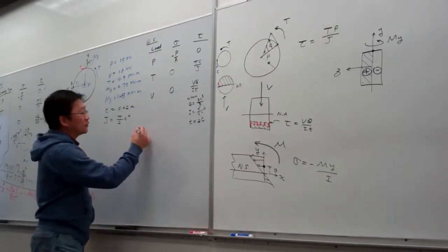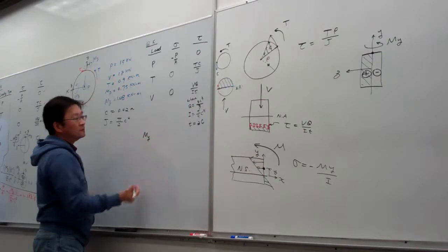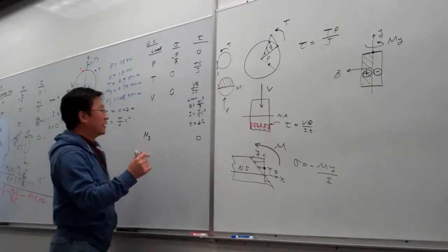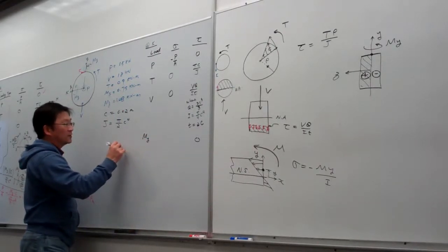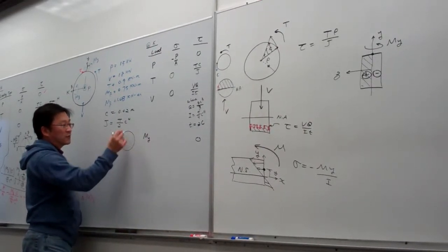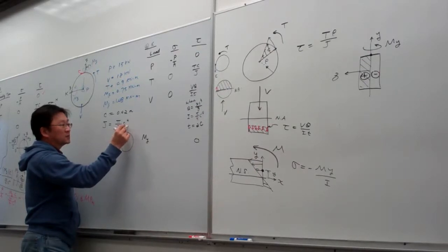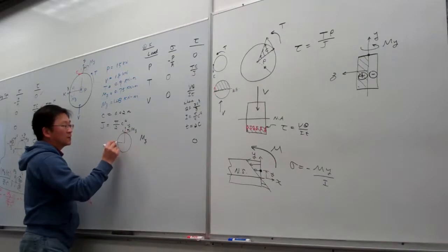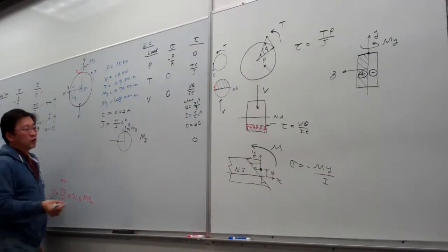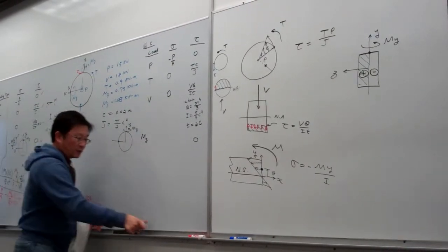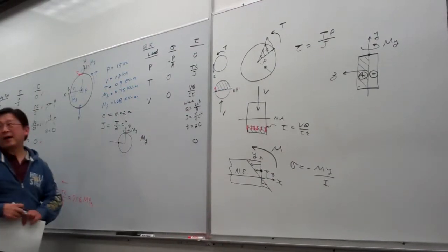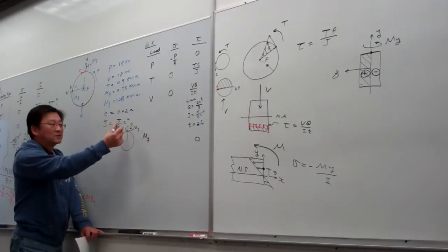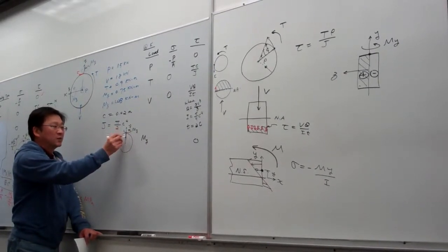And now we go to the MY. And this one is 0 for the shear. And for MY, again, let me draw this one here. So this is a cross section, and this is the Y, and MY is in this direction. This is a point. For this case, we determine our neutral axis. For pure bending, the neutral axis is the axis about which the bending is applied.